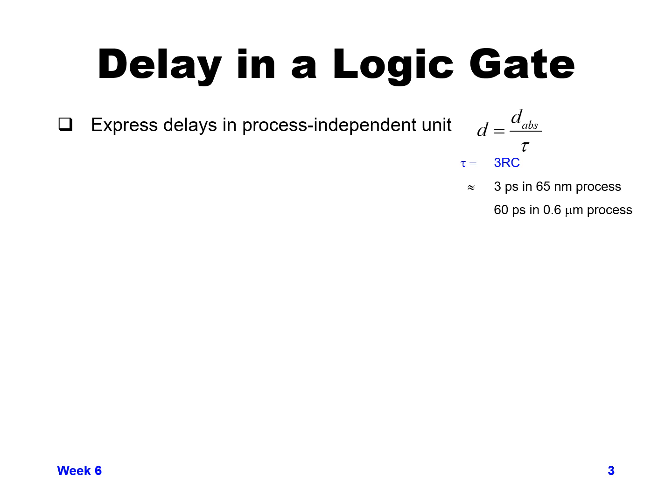But the absolute delay would be very different from one process technology to the other. Again, if we go from one process technology to the other, in both cases we would be talking about a D of 1, but the absolute number would be very different. So that's a key thing to note. So we're going to normalize everything to be process independent.